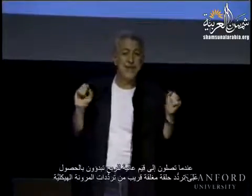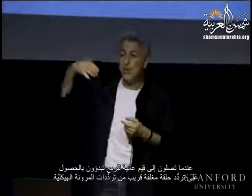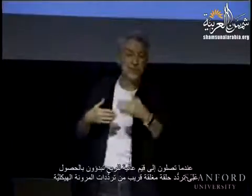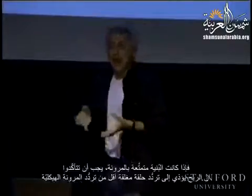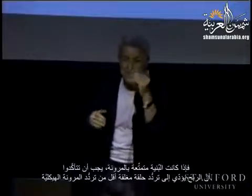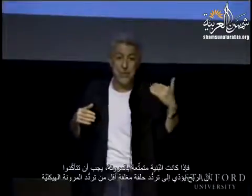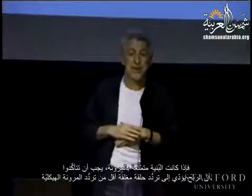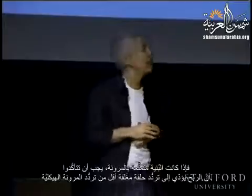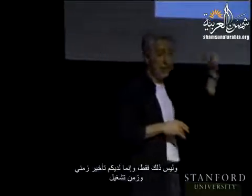Higher gains, you start to have a closed loop frequency closer to your flexible structural frequencies, and that leads to instabilities. You excite those modes. So if you have flexibilities, you have to make sure that your gains result in a closed loop frequency below your structural flexibilities. And not only that, you have time delays in the actuation.